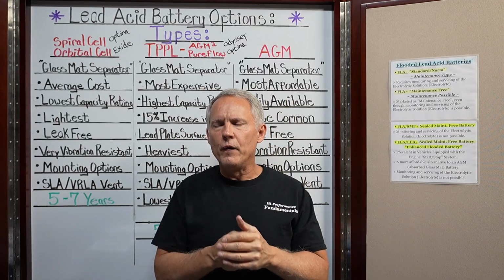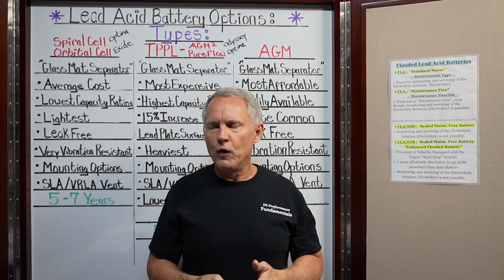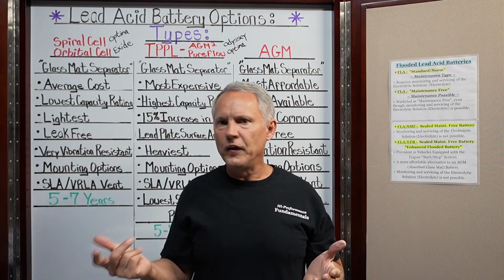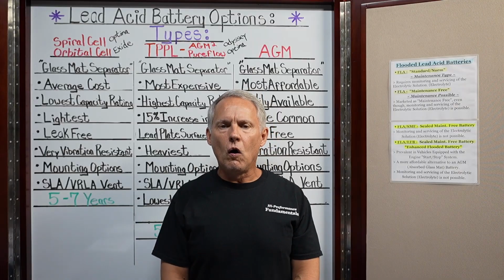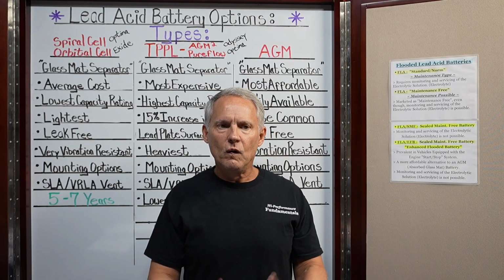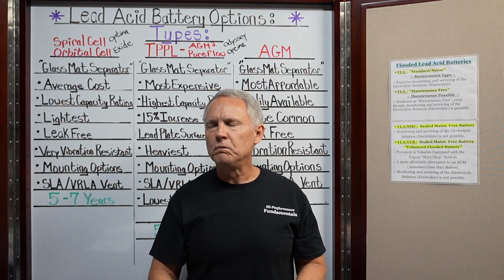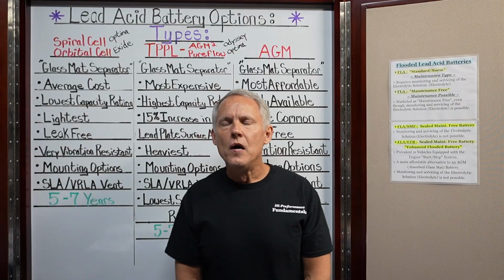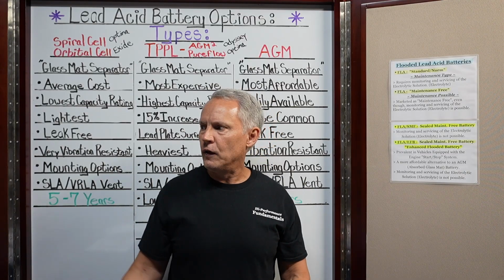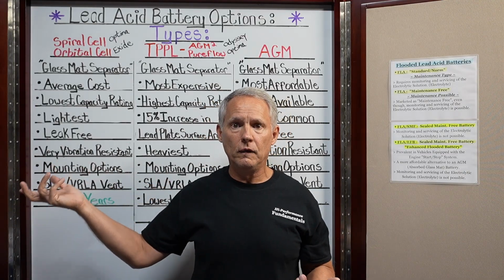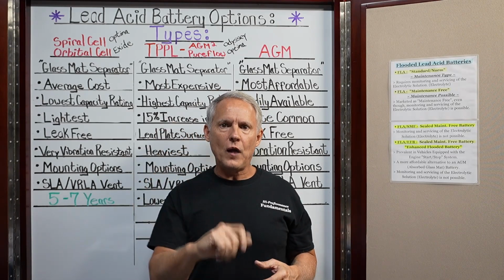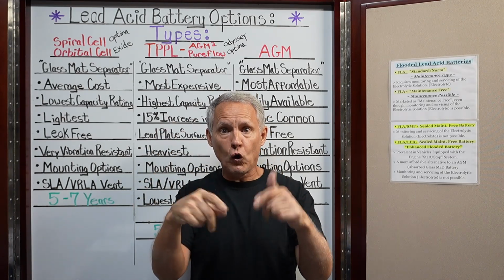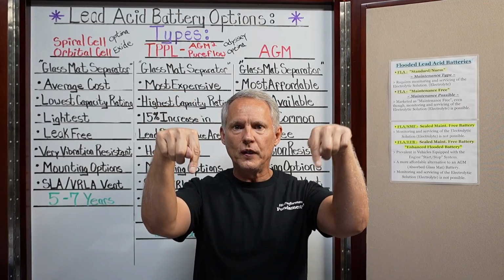Okay, so let's talk about this. Instead of a 12 volt battery, why would you want a 14 volt battery, or a 16 volt battery, and what are the things you've got to be a little careful about there? Let's talk about voltage sag, or voltage drop. Let's say you have a standard AGM or a standard liquid lead acid battery in your car, and you're monitoring voltage at the battery as you crank the engine over.